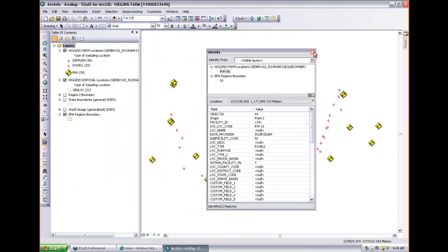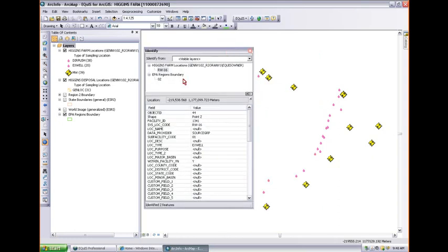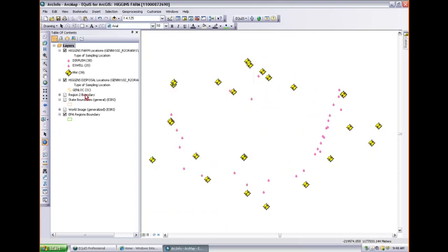All the symbology is customizable via what ESRI calls a style gallery. It's just a database of symbols. You can put this database on your network for everyone to share, and this helps everyone have consistent maps. So everyone's monitoring wells are going to be red, borings will be brown. If you have some kind of production department that you send your maps or documents to, they'll love you for this, because I remember that in consulting they spent most of their time trying to make everyone's maps look alike. With this style gallery, you can assign one or two people to come up with these symbols, put them on the network, and then you'll have standards in place.